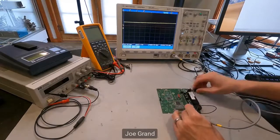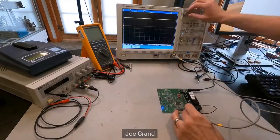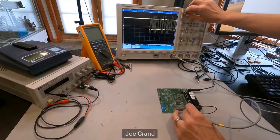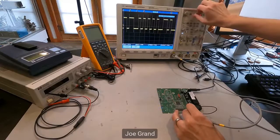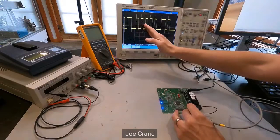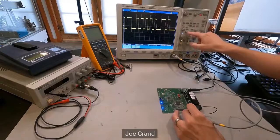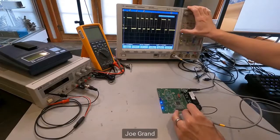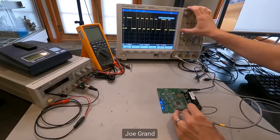So I'm going to hold my probe there while I power it on. And again, we're generally going to see information on power up. And that's what I'm trying to do here. So we can see some activity here. This ends up being what's called the UART interface. And we might not actually know that yet, but if we look at the signal, we can see, oh, everything is kind of an even multiple of each other. And that's a good clue that it's an asynchronous data stream. And I'll get to that in a little bit. But what we can do here is actually manually measure the width of 1 bit. And that's going to give us a good clue about what type of signal this is.